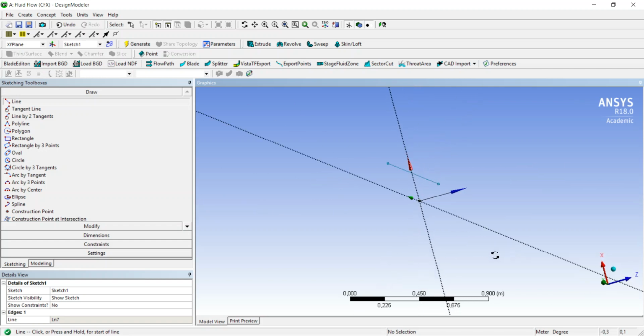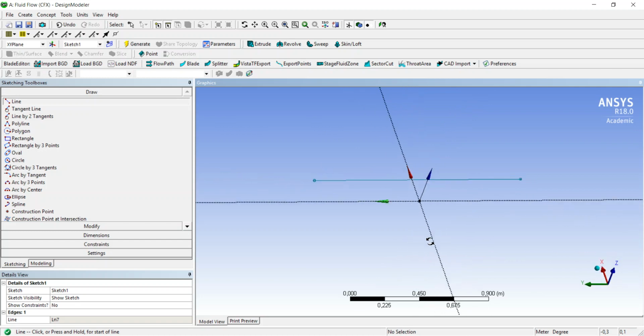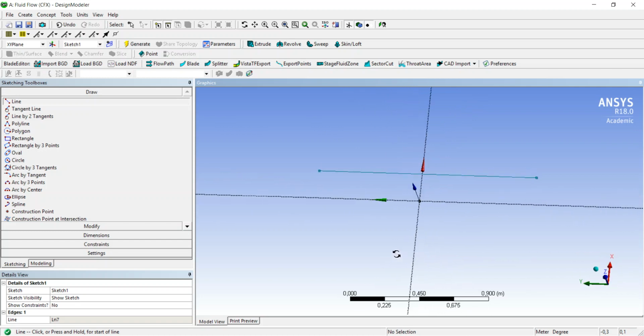You can again use pressing the mouse wheel to look carefully at your line. Now go to the left end or to the right end of the geometry until it's highlighted in red color. Now you can press again the pencil and draw a second line in -y direction. Again, left mouse click, you have your second line.